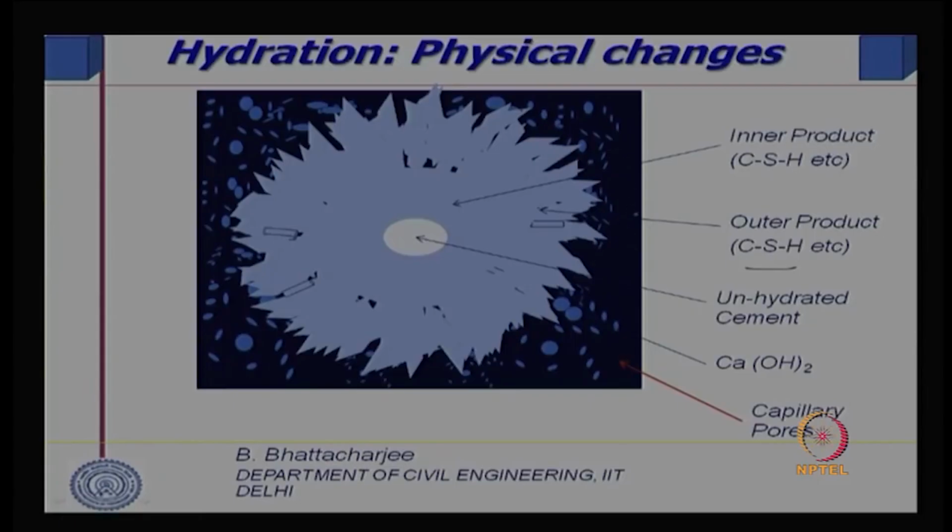But remember, a large quantity of pores will remain at the initial stage, unless you have very little water, which means less space to be filled by the solid products of hydration, and the continuous reaction progresses over a long period of time. We will look into this in more detail later on.